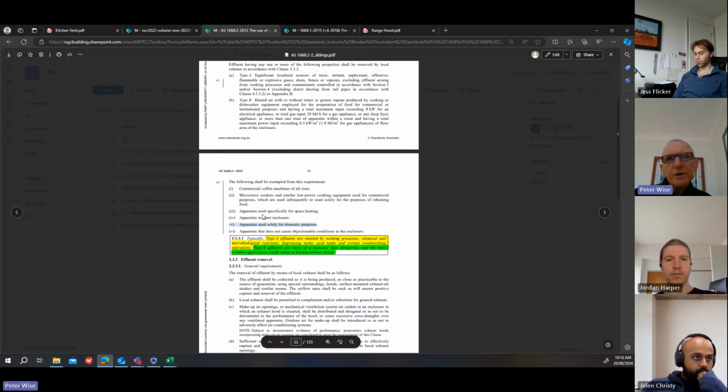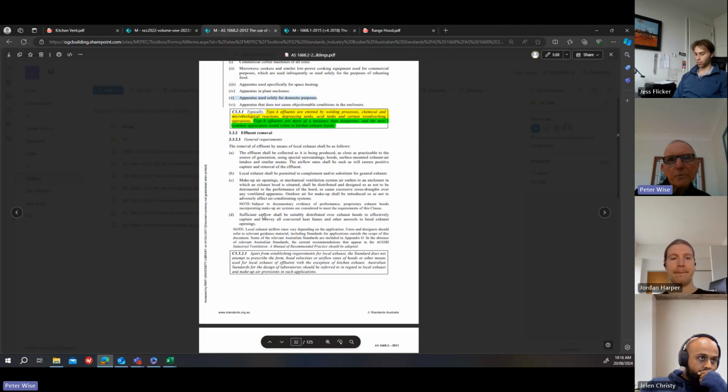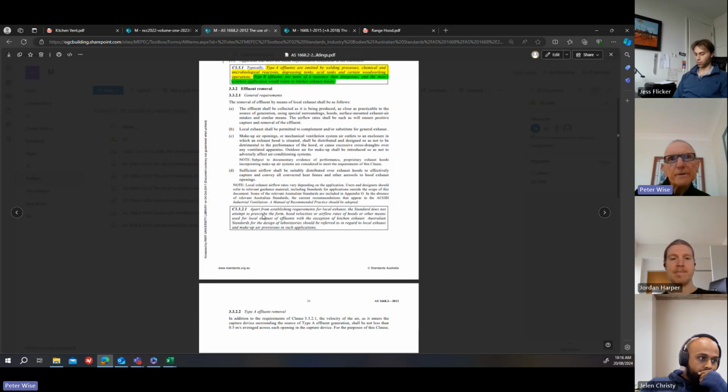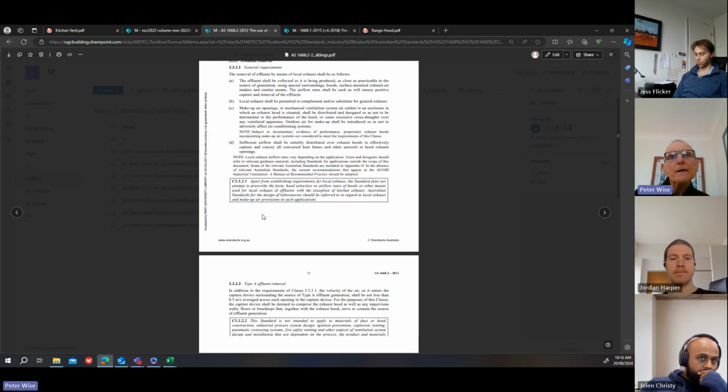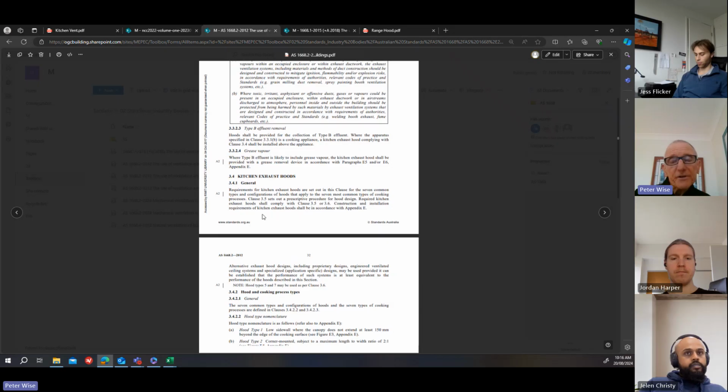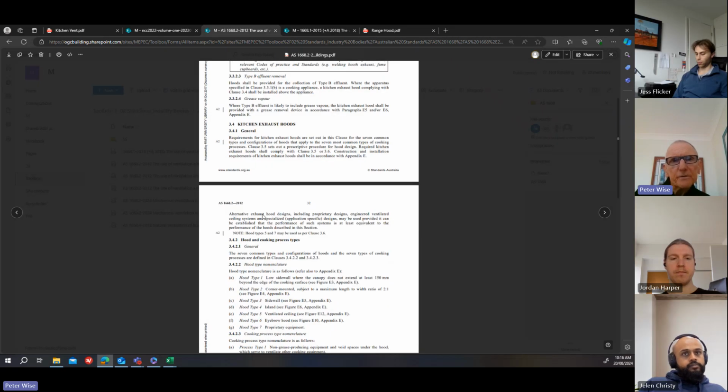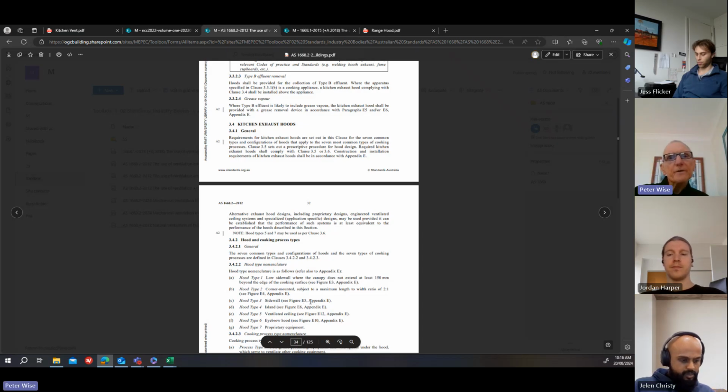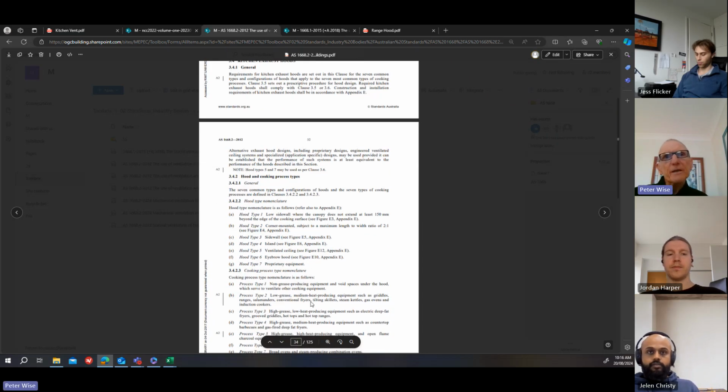But normally that will be presented to you. That won't be something that we will offer. The builder would say, we're going to use, let's say, a Holton exhaust hood, model such and such, and then they'll provide you with details of the airflow rate requirements and the pressure drop through the hood, and then that will become part of our design to incorporate that into the mechanical design.